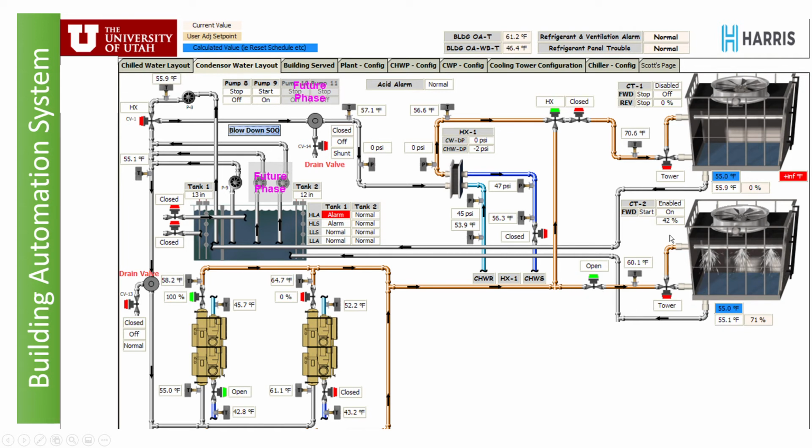So the other thing we saw out at the cooling tower was this three-way valve. Remember the very first brown pipe that we saw? That valve was either sending water up through the fill, or it can bypass if it's really cold outside. And the water comes back into the plant, and then this is the sump that we were standing on top of that had the concrete and the really big vertical turbine pumps. These pumps look like really little dinky things, but in fact they're giant. I think these pumps are 250 horsepower. One of the pumps in the plant I saw nameplate was 250 horsepower. So there's a lot of horsepower going on here.